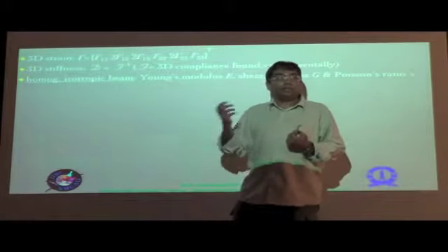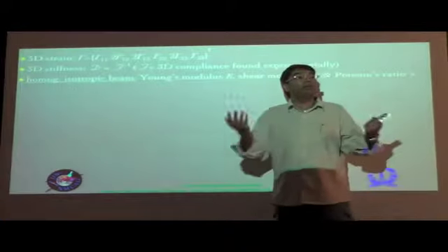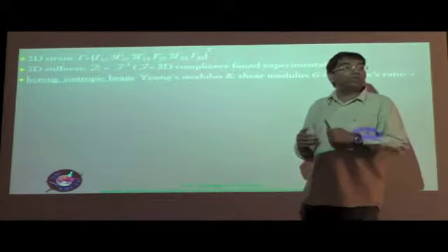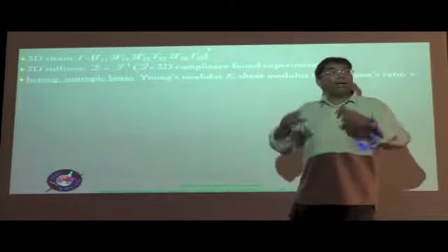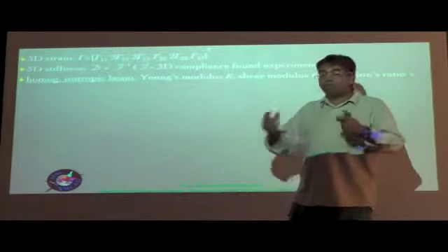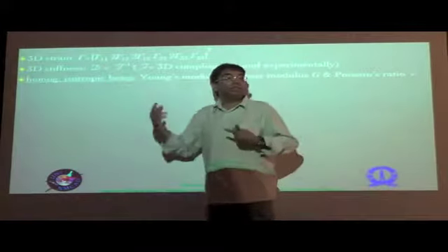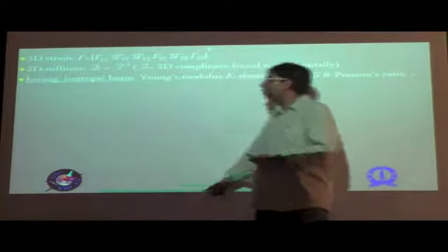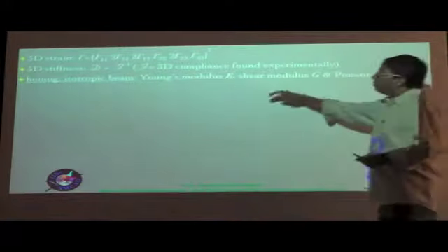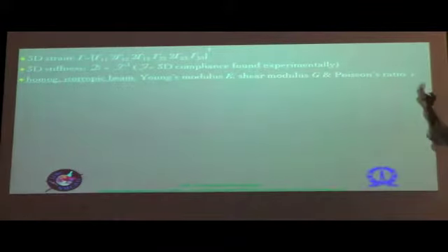So in most experiments you apply stress in one direction, determine the strains in all the other directions, including of course the shear strains, and you populate the F matrix. Once you populate the F matrix using that experimental and numerical procedure, you have to invert that matrix to get your D, and it's more convenient to utilize D for most of the mathematical modeling, right? So in the case of a homogeneous isotropic beam, just 2 quantities can determine this entire D.